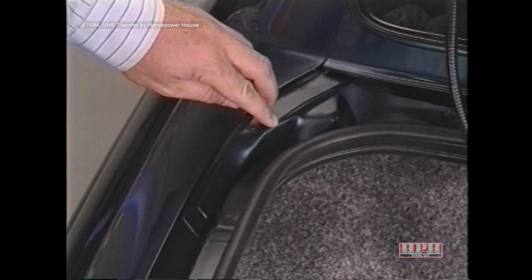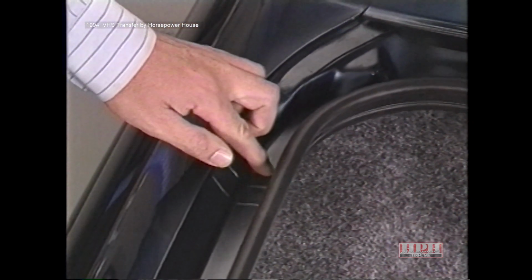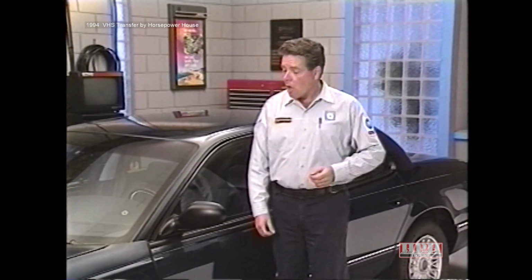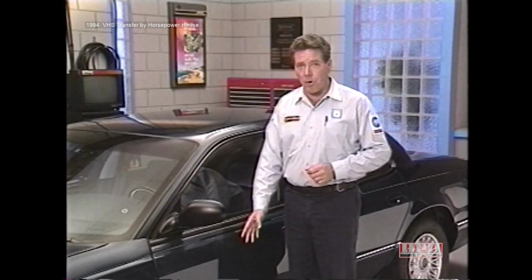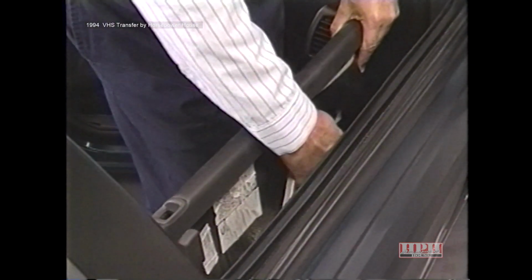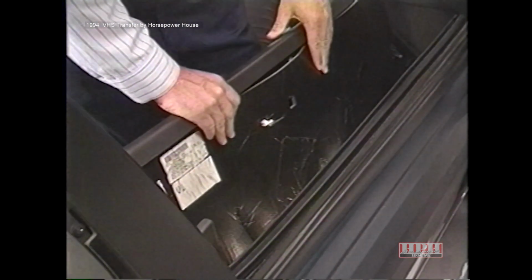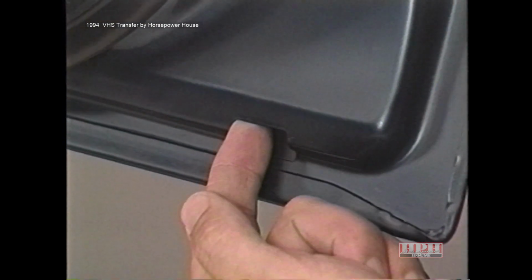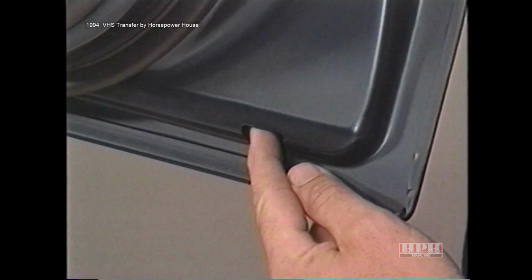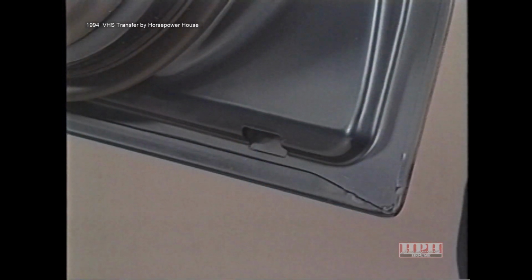But what about body seams or joints on the vehicle? A poor seal could also occur at one of these areas, so it's important to keep that in mind when trying to locate a water leak. In addition, water can enter the doors at the belt weather strip and fall to the bottom of the door. A water shield is installed between the door and the trim panel to keep water from leaking inside the vehicle. And holes in the bottom of the door are designed to let water drain out. Problems may arise if these become plugged.